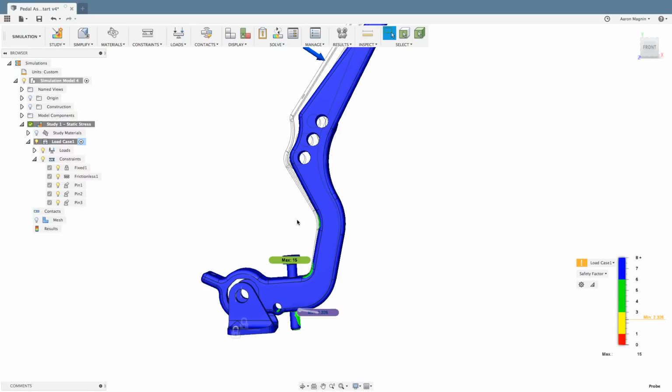The reason is that there's a potential for what's called a singularity. When I post the recording for this, I'll link to a quick tip we did on singularities. It's common in every single finite element analysis. It's related to the mathematics behind it and the faces that can get created in CAD. So it's something to know about, and to ignore when you can.